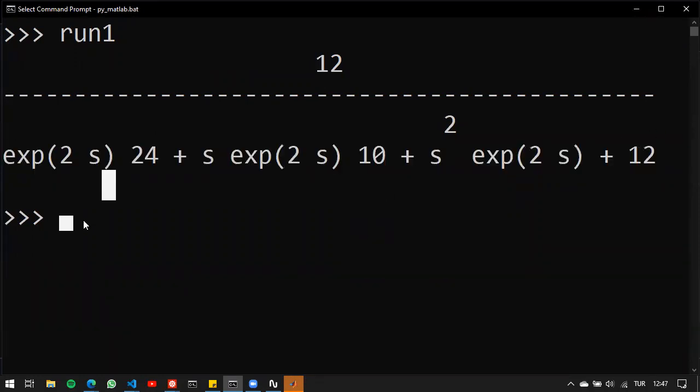And the characteristic polynomial is by definition the polynomial that appears in the denominator. But here the denominator is not a polynomial, because by definition a polynomial uses just the s powers and their linear combination. But we have a nonlinear term here, the e term. So therefore, this is not a valid transfer function, or we cannot acquire a valid characteristic polynomial.